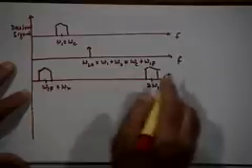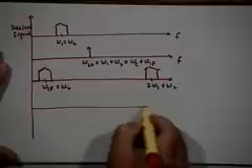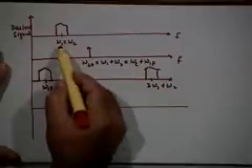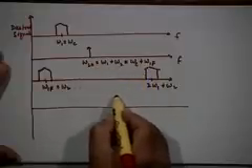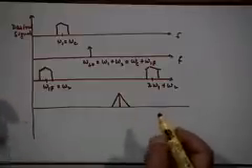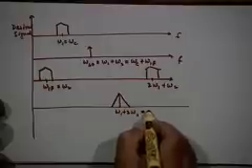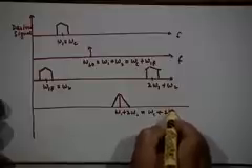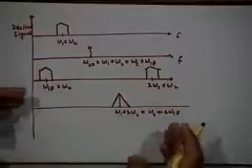This is what you want. This is the desirable thing. The undesirable thing is the image frequency. What is the image frequency here? Omega 1 plus 2 omega 2. So, let us say it can be somewhere here, and let us say there is another message signal present there. The second signal, there is a radio station whose center frequency is omega 1 plus 2 omega 2, that means omega c plus 2 omega IF. Suppose there is a second transmitting station which is transmitting at this frequency.